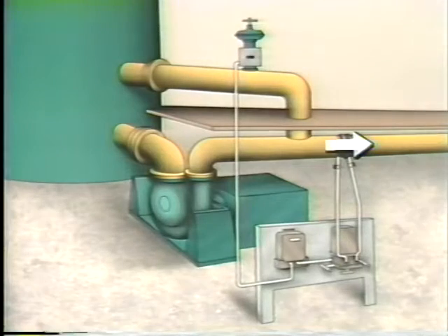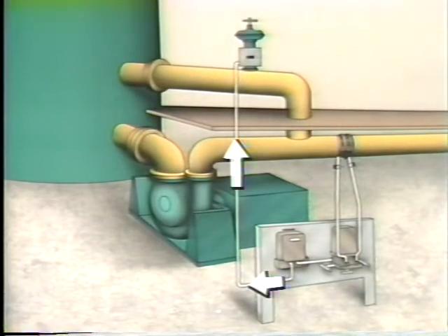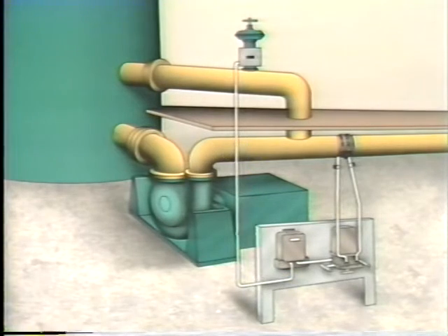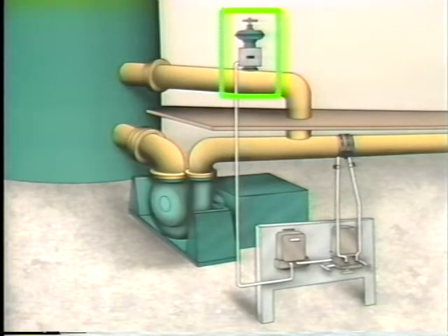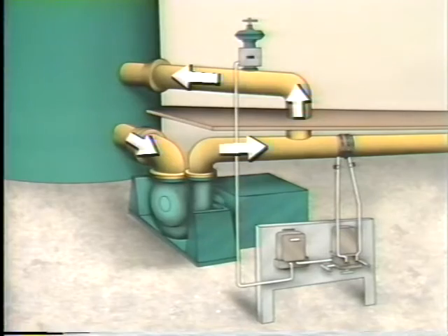So a small change in the discharge flow below set point will result in a large change in the controller output. This in turn opens the valve most of the way and ensures that the flow through the pump is more than enough to keep the pump from overheating.